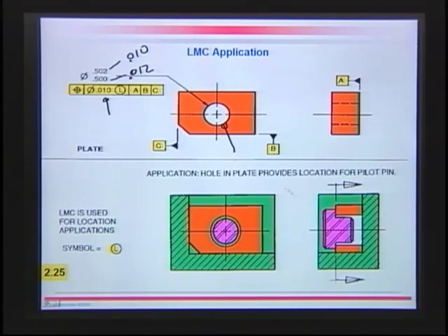But when the hole comes in a little bit smaller, you see, rather than a 502 hole, the hole comes in at 500. When you put the purple pin inside of the hole, well, the size is smaller, so it doesn't rattle around as much. Well, then you can be off by the amount that the hole got smaller by. So basically what you're telling manufacturing is, look, you're putting a hole in here for me. I got this purple pin that fits in a hole. If you make a big hole, then when I put my pin in, it rattles around, right? And I'm trying to keep it on center as much as possible. So I'll tell you what, if you make a smaller hole, you can be off more than when you make a big hole, right?